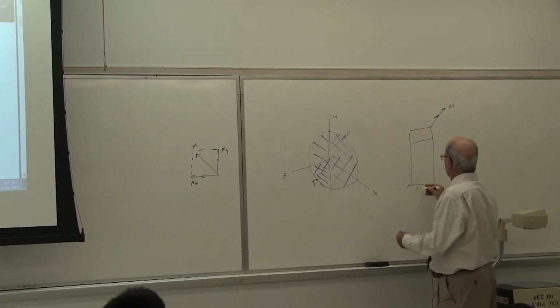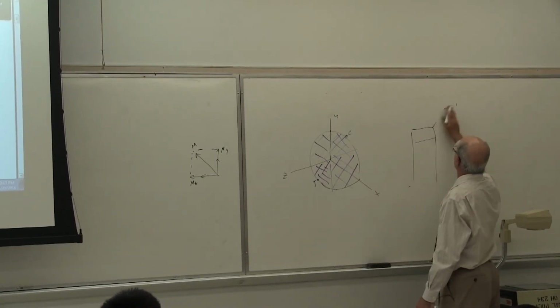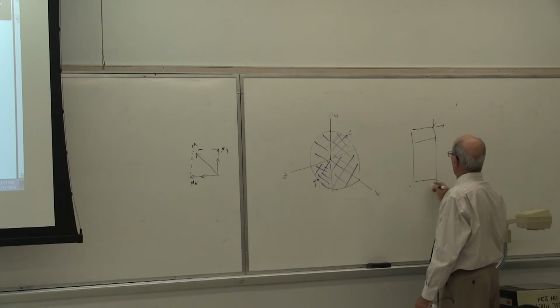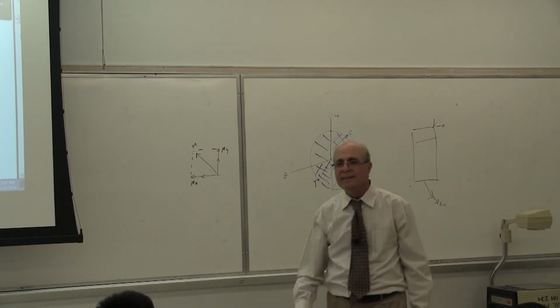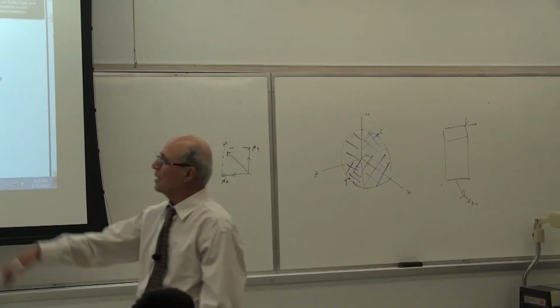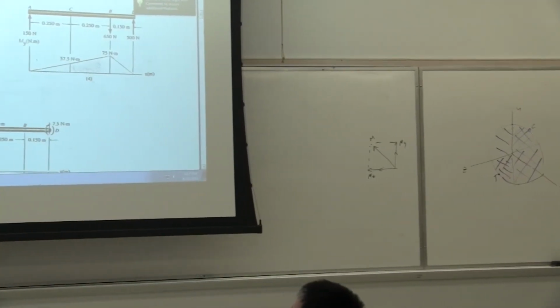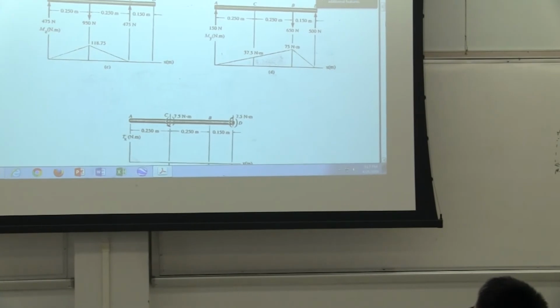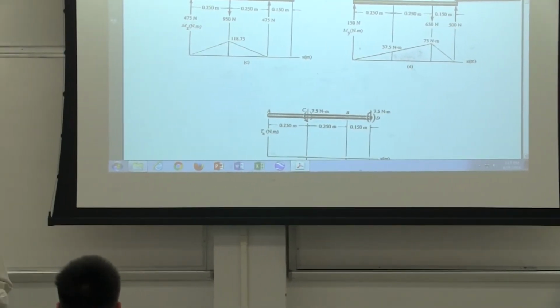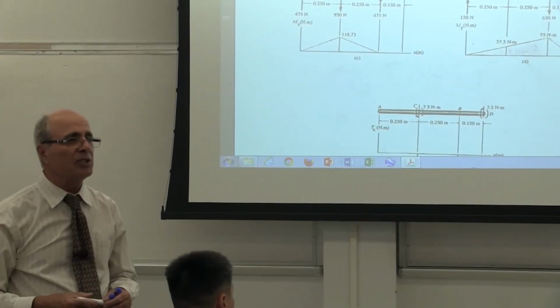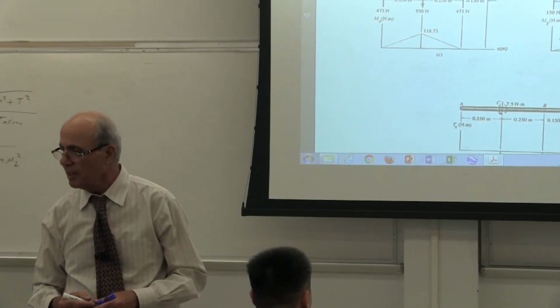Or at that cross section, let's say in this cross section, I'm sorry, you have some kind of load here. You end up with a moment vector here, which is Mx, My, and Mz. The magnitude of that moment goes into this equation and gives you the size of the shaft. Is that correct or not? Did you see what happened? Regardless of which one is torque and which one is bending.